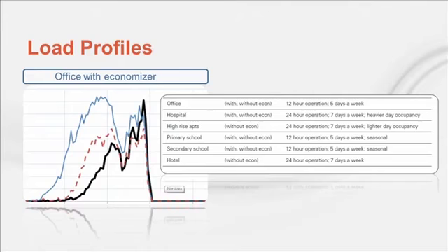The load profiles are a result of various ASHRAE standards efforts, along with Pacific Northwest National Labs. They've created a library of annualized load profiles for various building types in all weather zones. The MyPLV tool incorporates 200 of these load profiles within its database. By selecting both location and building type, MyPLV generates one of these 200 load profiles.